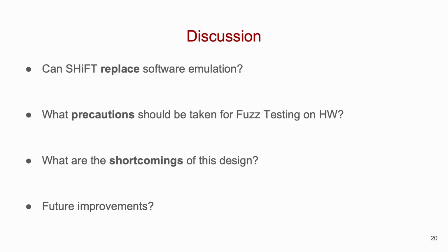Secondly, SHiFT's design requires two tasks to fuzz a binary. This compels use of FreeRTOS for task scheduling, preventing bare metal application testing. While dual-core configuration allows bare metal testing, it is significantly less performant than the single-core configuration. Most embedded devices do not possess multiple cores to increase the performance.